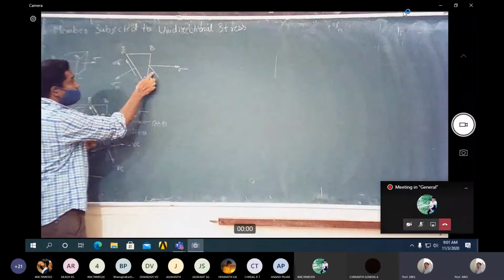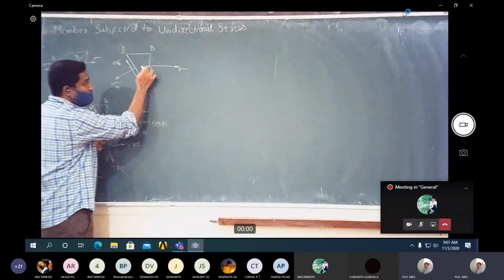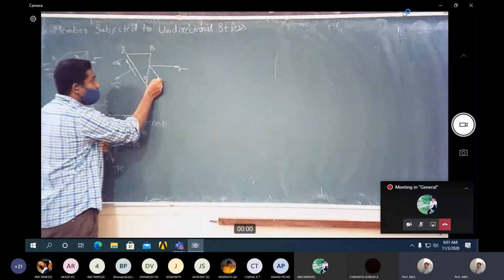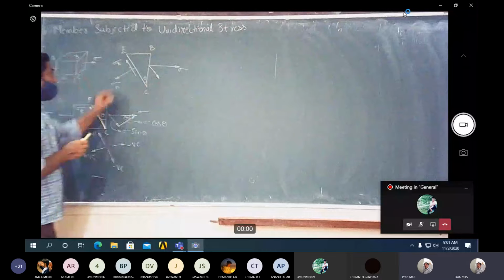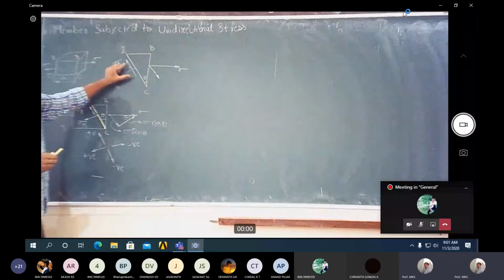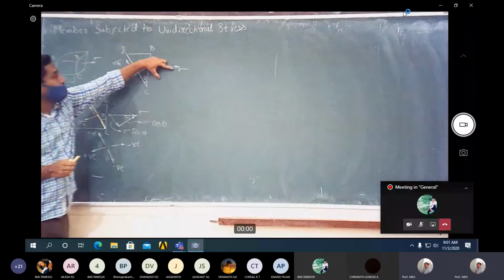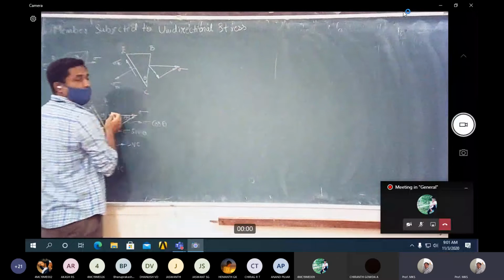So you'll draw this line parallel to the tangential stress. The direction has to close with the applied stress, so its direction will be in the reverse direction. Next, I have drawn the parallel line to the tangential stress. Now draw the parallel line with respect to the normal stress with the ending point. So this is the ending point, and that has to connect with the applied stress, right?